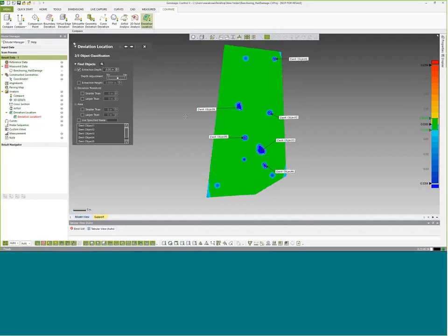Now, besides that, we found these objects, but what we're really going to do is we want to maybe classify things down a little bit more. So we have a deviation threshold and area. Maybe you have a certain square area of an item that you're looking for that you would want to be suspect for repair, or really qualify something for rework. So you could select either one of those. I'm actually just going to use deviation threshold and say we're going to look at stuff that is of a certain depth overall that's going to flag an item for us to investigate in person essentially.